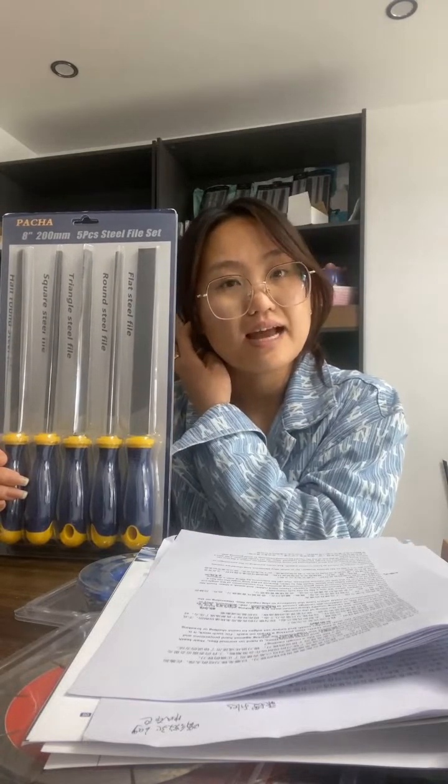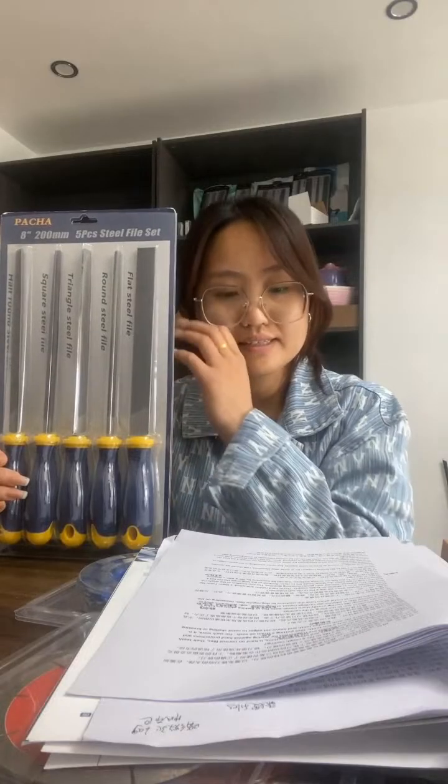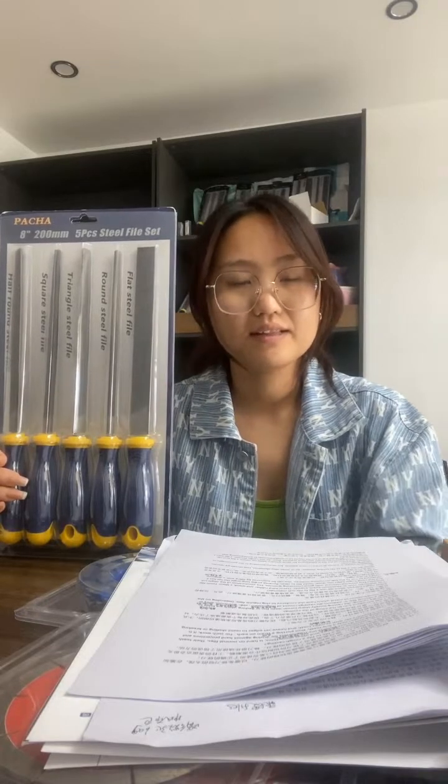And next, I will introduce you to the filing of die castings. Like foundry castings, die castings have sharp corners, webs, fans, or flashing which are liable to damage normal files. In addition, die castings consist of magnesium, zinc, aluminum alloy, or similar combinations of metal which have the tendency to clog regular files.